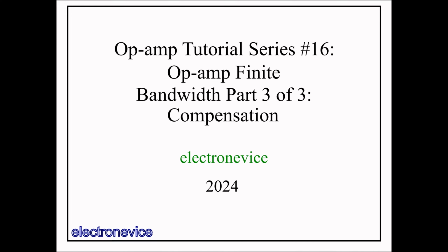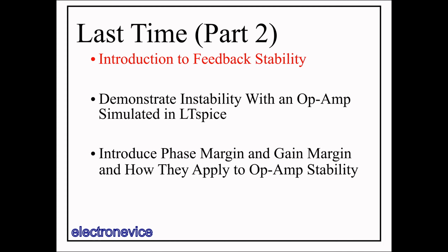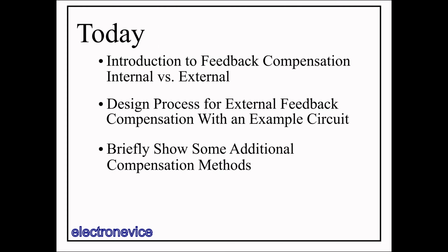Hello everyone. Welcome to episode 16 in the Op-Amp tutorial series, Op-Amp Finite Bandwidth Part 3, Compensation. In Part 2, we introduced the concept of instability in op-amp feedback circuits, demonstrated instability with an op-amp simulated in LT-SPICE, then introduced the concepts of phase margin and gain margin, and how to use Bode plots of loop gain to evaluate the stability of op-amp circuits.